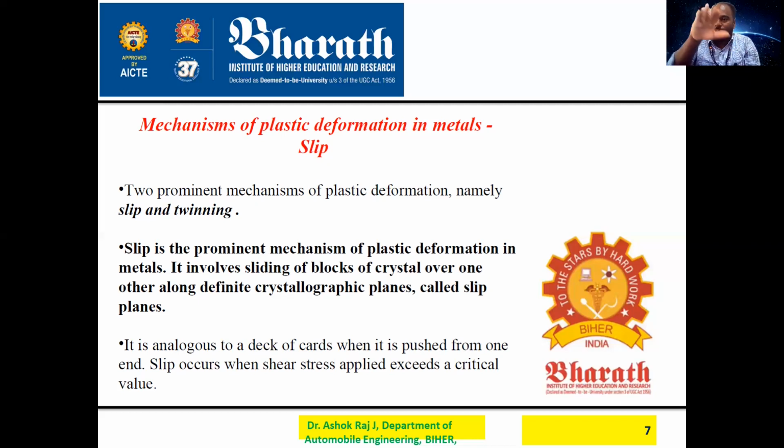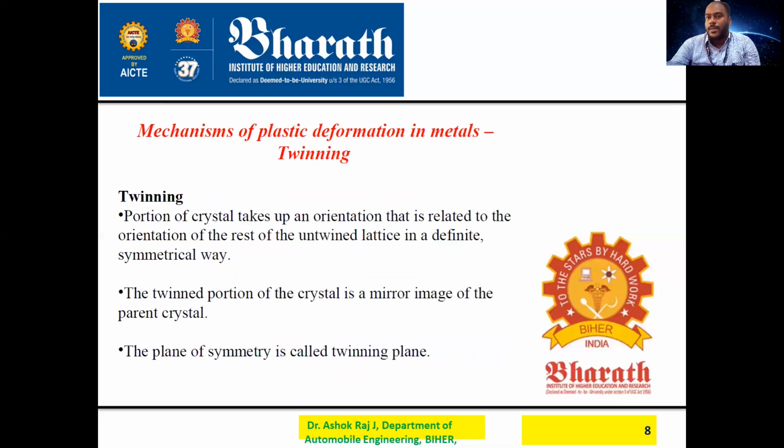You can see steps like that. Only slip will appear when you look under the microscope, when it is pushed from one end to another, like the cards I described. So slip occurs when the applied shear stress exceeds a critical value. Only if you apply the critical value will slip take place.